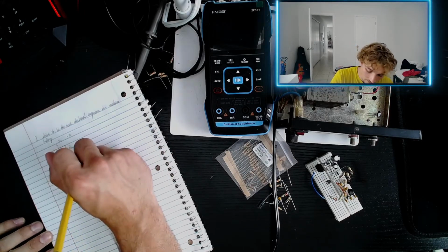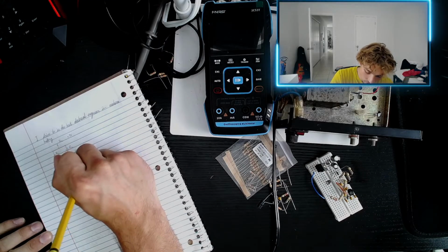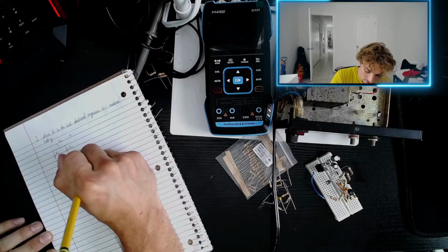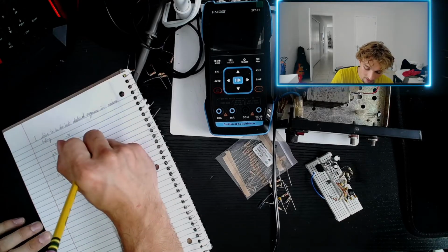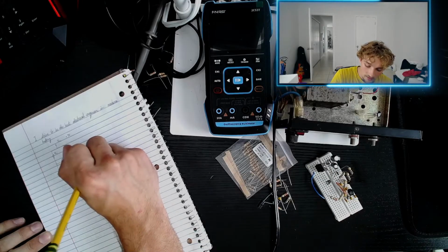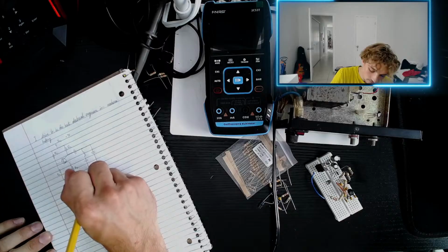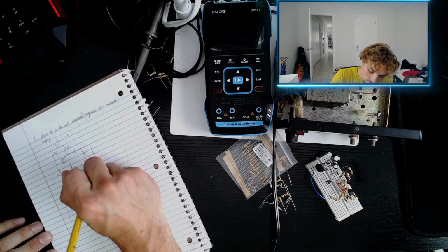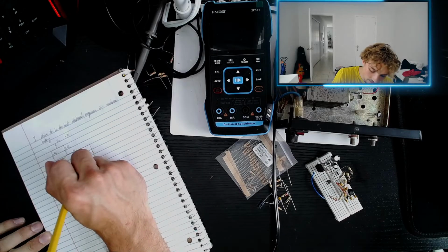It's a direct current. And now this is our topology for our specific Colpitts oscillator. We're going to tap here in between the capacitor and inductor, and then we have the second capacitor in parallel. Grounded here, and this is our feedback network right here.